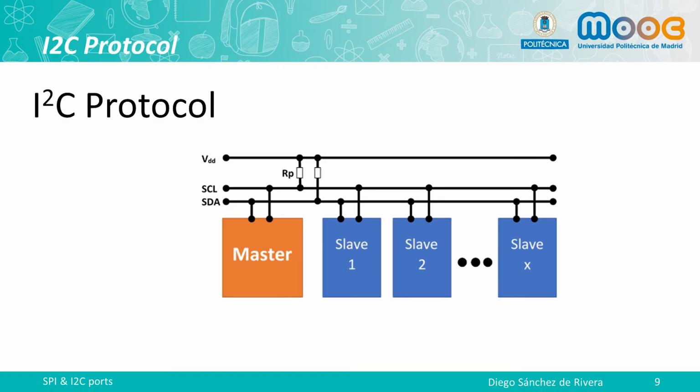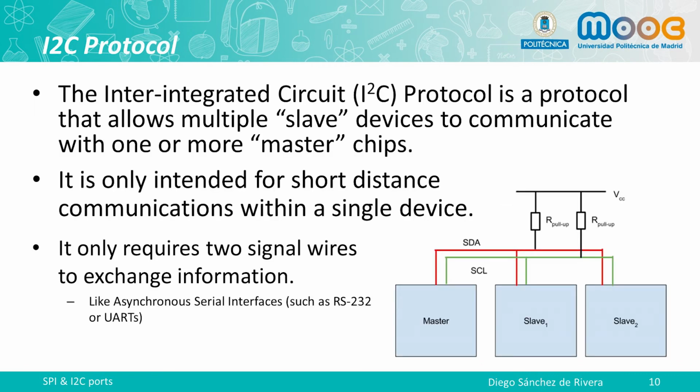Now let's focus on the I2C protocol, another popular protocol that allows external device connection in our Arduino boards. We will see the main differences and advantages over the previously discussed methods of communication. The I2C communication bus is very popular and broadly used by many electronic devices because it can be easily implemented in many electronic designs. The easy implementation comes with the fact that only 2 wires are required for communication between several devices. I2C is also serial and uses 2 pins but works completely differently than asynchronous serial.